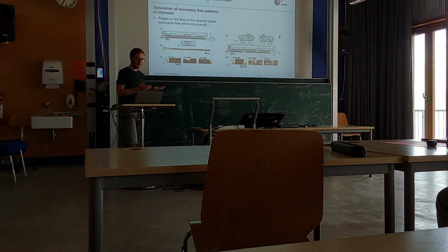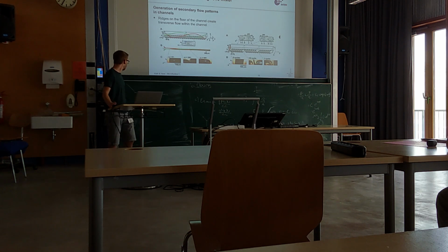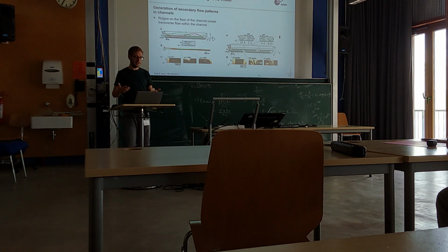Okay? So using just hydrodynamic principles or using some kind of geometric features like bending a channel or making the geometry slightly more complicated, you can induce some irregularities to the flow field, so you don't have pure Hagen-Poiseuille flow, but those vortices, and this leads to enhanced diffusion or, let's say, mixing by convection. Alright, so those are two very commonly used methods to enhance mixing in pressure-driven systems.